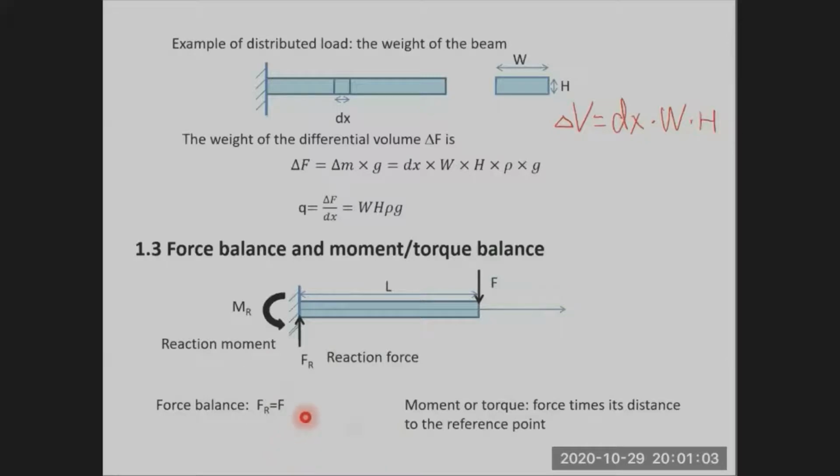No, it's not. Because this force also generates a moment which tends to rotate this cantilever beam. How large is the moment generated by this force? M is equal to F times L, the distance.